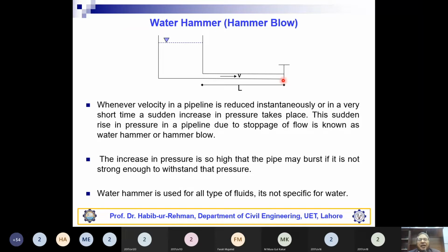What is the practical example of valves in case of hydropower plants? Yes, to increase or decrease the discharge. In case of impulse turbines, that is a spear head needle, and in case of reaction turbines, the governor. Those are movable guide plates. The function of the governor is different. The function of the governor is to keep the RPM of the turbine shaft the same, equal to the normal speed of the turbine, even when the load on the turbine changes. Okay, that is the function of the governor.